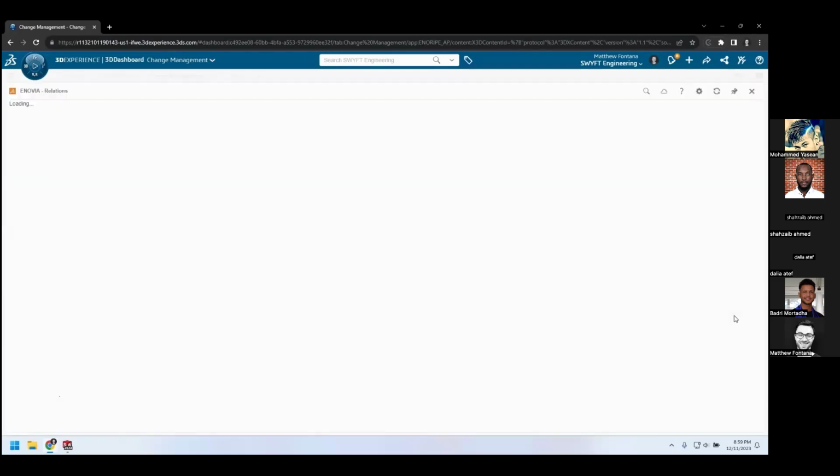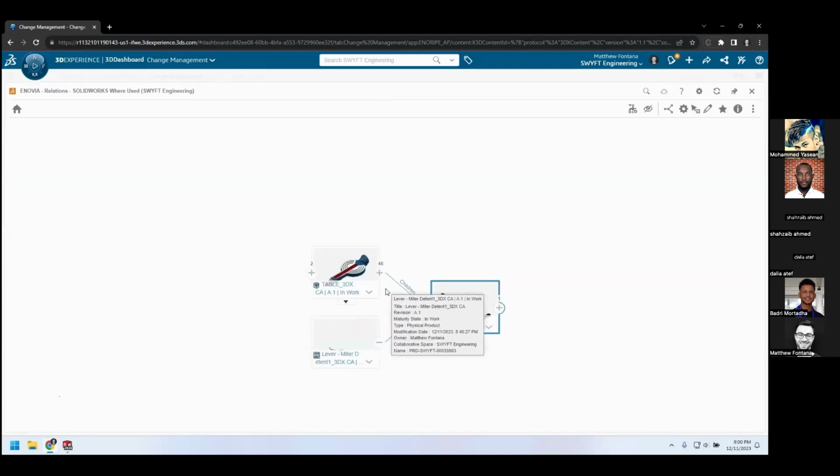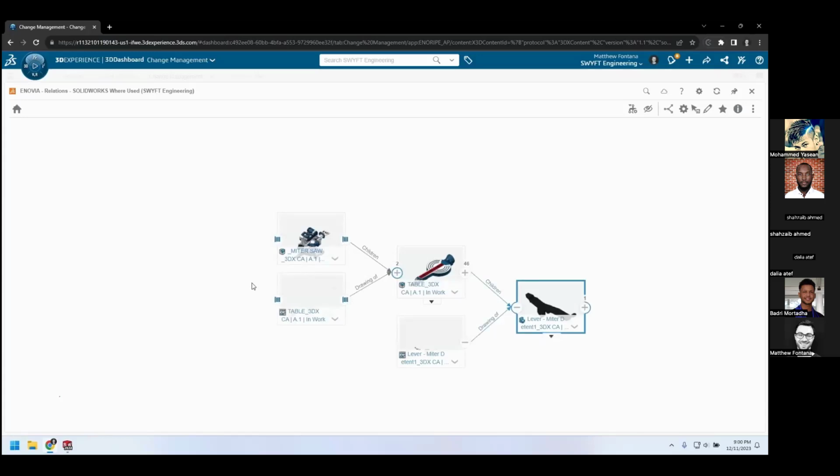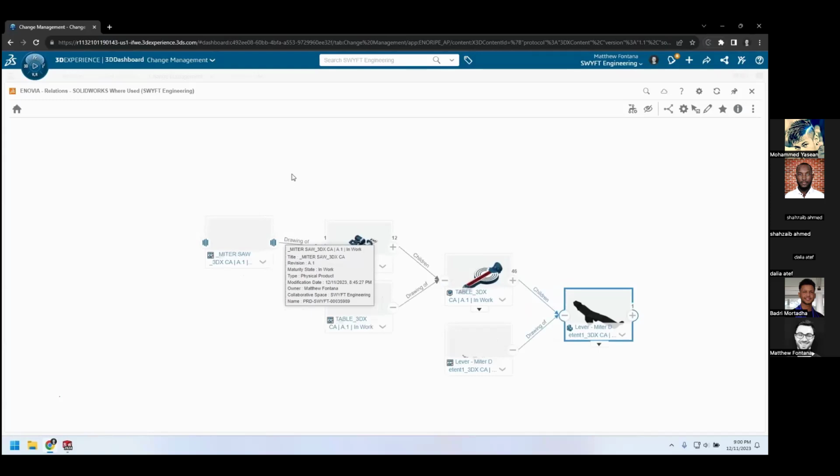Also, we can jump into a change assessment, which is really important when it comes to getting into larger assemblies, more complex structures. Once you change a part, you may not have a good perspective of how big of an impact that's really going to have. So if I change this part and I look at all the parents in this relational explorer, I realize that I'm not just going to have to change that part. I'm going to have to confirm that it works in the subassembly, the main assembly. I'm going to have to update the drawing for the part, the drawing for the subassembly, the drawing for the main assembly with different revision information. So there's a lot bigger of an impact than you may originally anticipate, and that may help determine whether or not you're actually going to make a change or not.